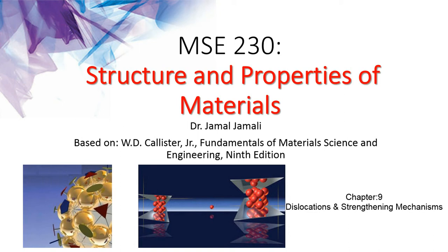Here, by having knowledge of dislocations and knowing the role that dislocations play in the plastic deformation process, we are able to understand mechanisms and techniques that strengthen and harden metals and their alloys, and therefore we go one step ahead towards designing and tailoring mechanical properties of materials.